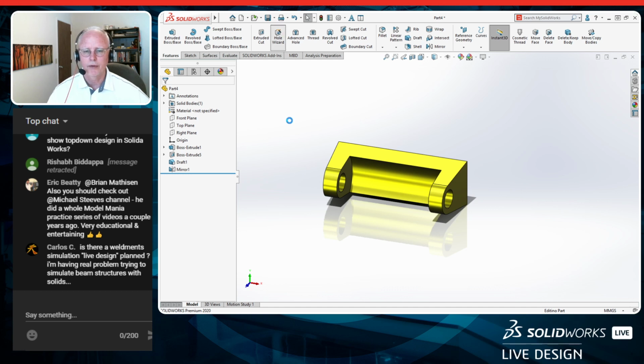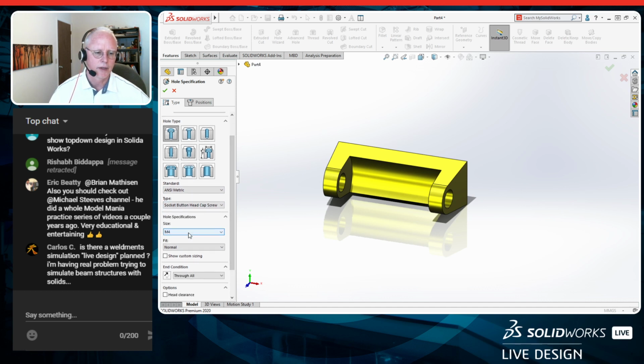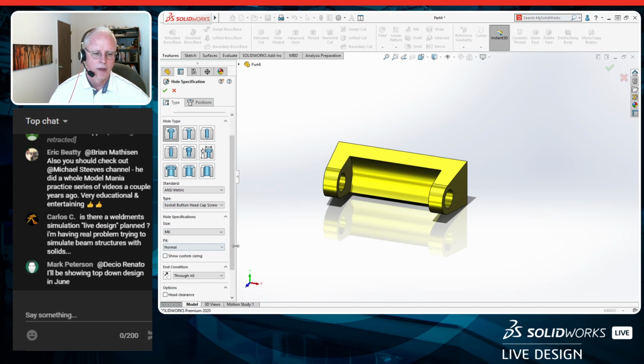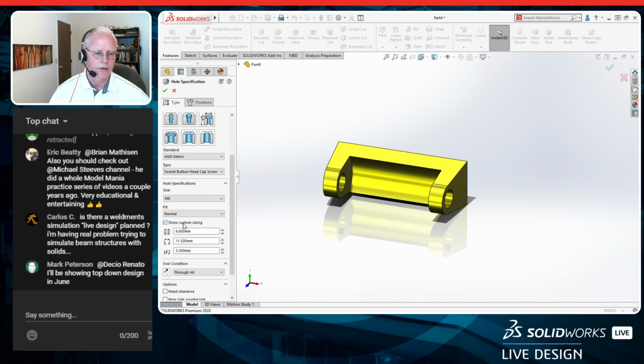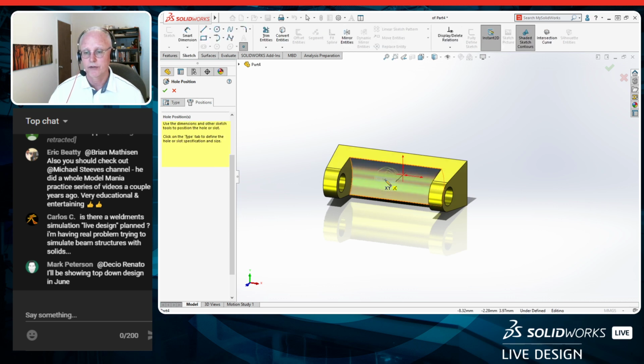So we'll do our whole wizard again. I said M6 counterbore for M6 button head cap screw. It's going to be an M6. And what I always like to do is take a look at my custom sizing. The depth is 3.3, so our depth is already correct, so we don't need to worry about that. Again, we'll go into our positions. Since I'm creating this whole wizard hole on a non-planar face, it's going to automatically take me into the 3D sketch environment. So I'll just choose this face here, and it knows to do that.